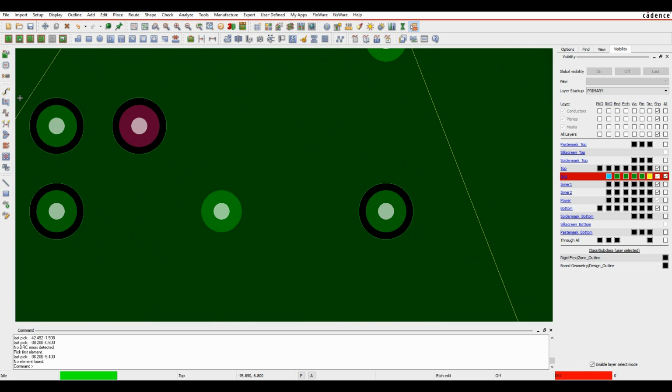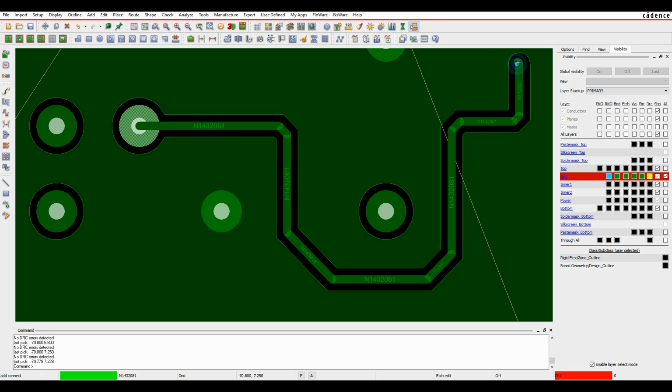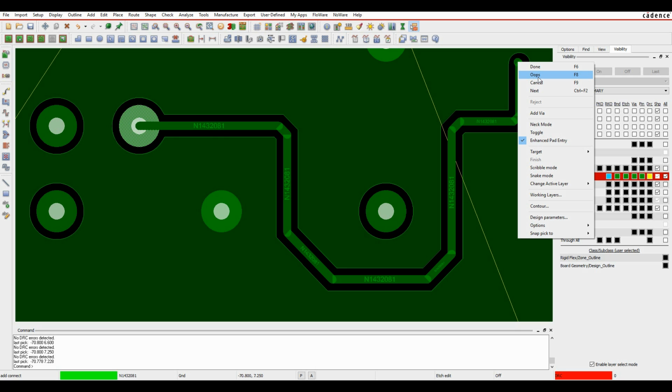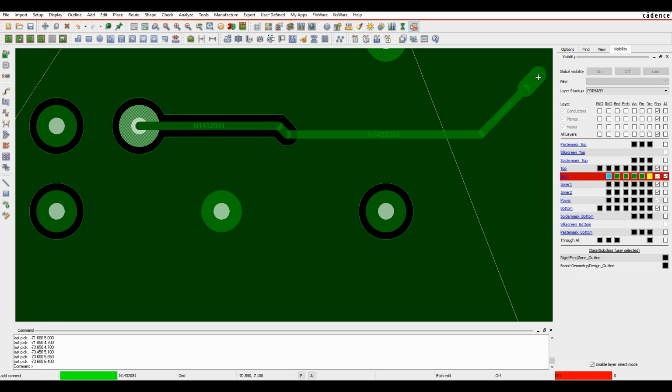So we're going to do some routing through a dynamic ground plane. I want to pick this net and start routing, and you can see that the copper shape dynamically updates to make any clearance as I'm routing through the copper. So I haven't got to worry about repouring the copper afterwards or doing it as a post-process. It's all instant. If I've made a mistake, I can literally use a right-click oops or press the F8 key. So we'll just press F8 to undo those objects, and the copper shape repairs itself.